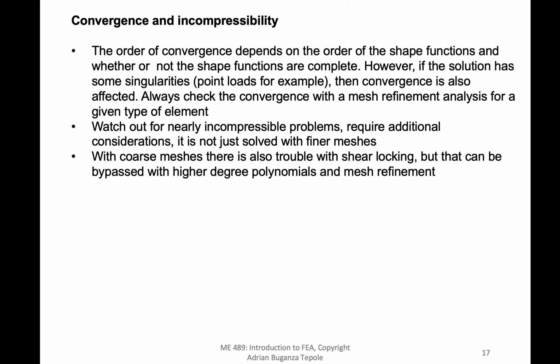So you refine the mesh again, and as you continue to refine, you should see that the solution stops changing. This is something that we did, for example, for the plate with a hole. As we refined the mesh, we got closer and closer to the analytical solution, and then at some point there's basically no change in the solution, even if you refine the mesh.